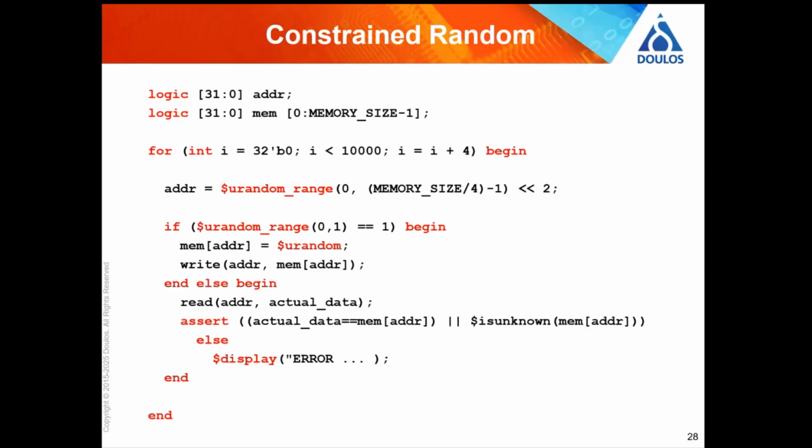And you can see that it doesn't matter about the syntax here. If you don't know SystemVerilog, if you don't know any hardware description language, you can see by the word random that appears on the 4th line down, we're picking a random address. And you can then see on the 5th line down, we're choosing a random number between 1 and 0. We're flipping a coin, basically.